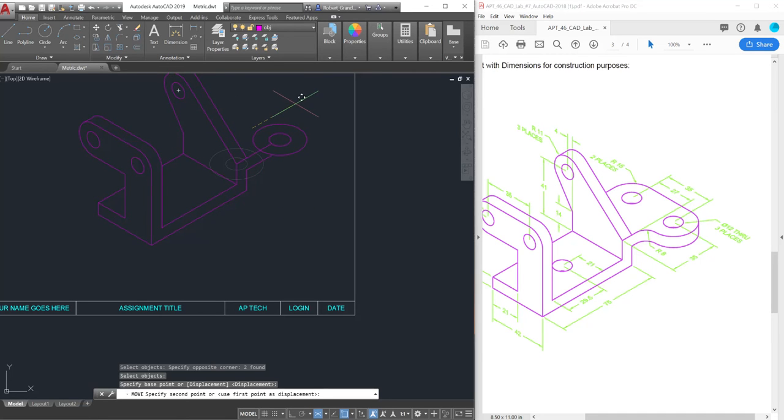And you can see I took myself out of ortho mode to be able to do some work up here. So I'm going to press F8, which will toggle ortho mode back in, and because I'm in draft mode setting, you can see it's restricting me to the correct direction. I'm going to type in 35 to move it 35 millimeters that way.